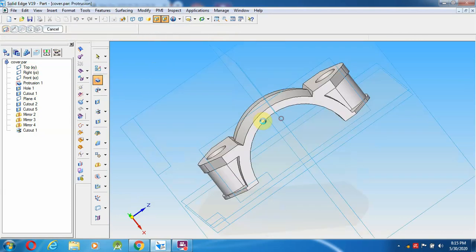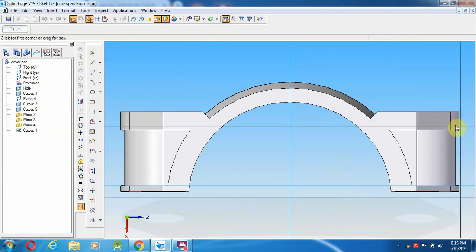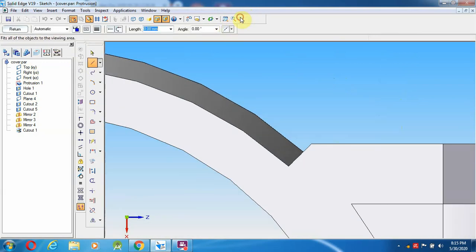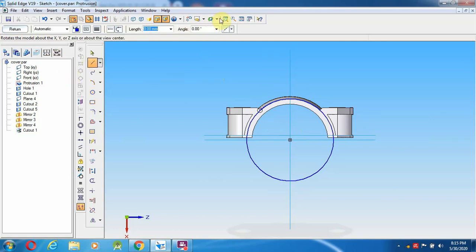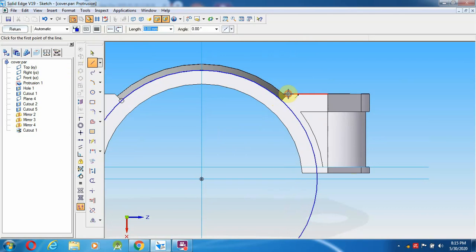Next time, other time, this time we will try. So go for the fit option first, select a circle from the middle up to this 55, then select a line from the particular thing, select the line from here to here, and again the straight line.